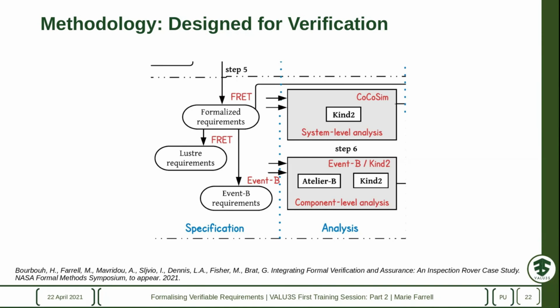Once we have formalized these requirements, we intend to translate them into CocoSim and Lustre. So Lustre is an intermediate language for CocoSim, which uses the Kind2 model checker. And that'll be based on the Simulink model that has been input by our industry partner.